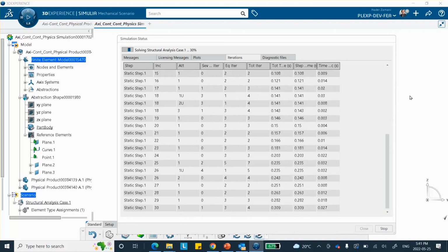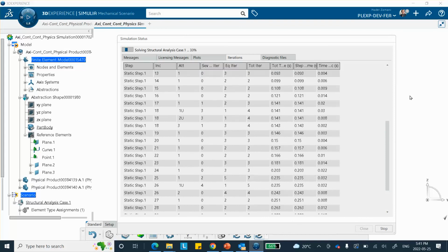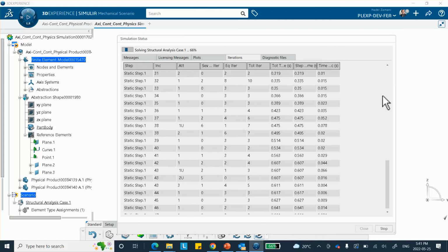We're not going to be interested in comparing this with that video tutorial on ABAQUS CAE. It's just that the process is explained to you. The two obviously are not the same models. In the other one, the indenter is modeled differently. It's getting there. We're down to 0.5, 0.6. See, the step sizes are getting bigger. Initially, it will cut down on the increment, but as you go further along, things are going to go faster.